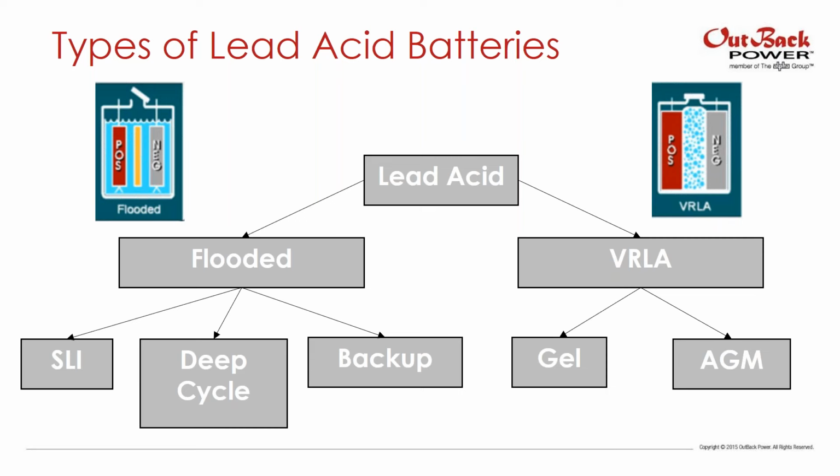They took the liquid electrolyte and added fine silica particles to thicken it. Basically they've suspended the sulfuric acid in an almost jello-like substance. Then 10 years later, we had another change to the lead acid battery. McClelland and Devitt of the Gates Corporation used an AGM, or absorbent glass mat, separator, and they effectively invented the maintenance-free VRLA.